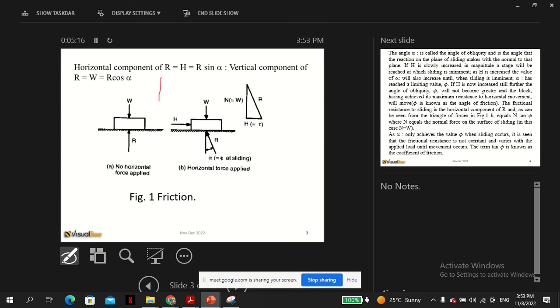Number two, this is the reason why, when you are doing the experiment, you vary this. You put a smaller value of sigma 1 and sigma 3, maybe this is 50 and this is, let's say, 30. If you draw it, you have a small Mohr circle.